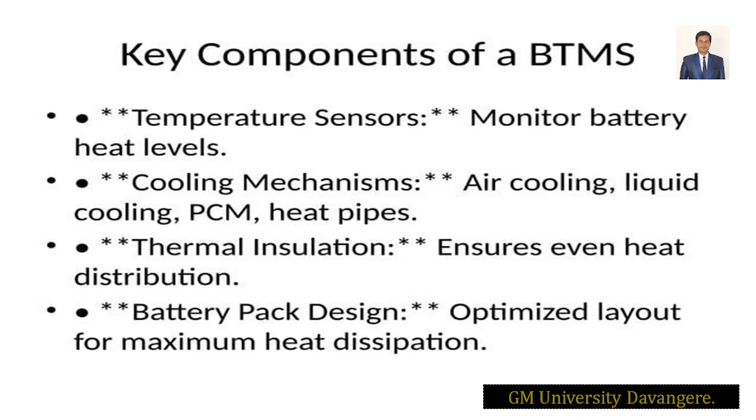So if the fast charging is around 20 kilowatts, what is the heat that has been produced? That is what you have to think about, right? So these are all the techniques we have to think about if the temperature is raised. What are the cooling mechanisms we can implement? That is active cooling or passive cooling, right? Air cooling, liquid cooling, or PCM or heat pipes.